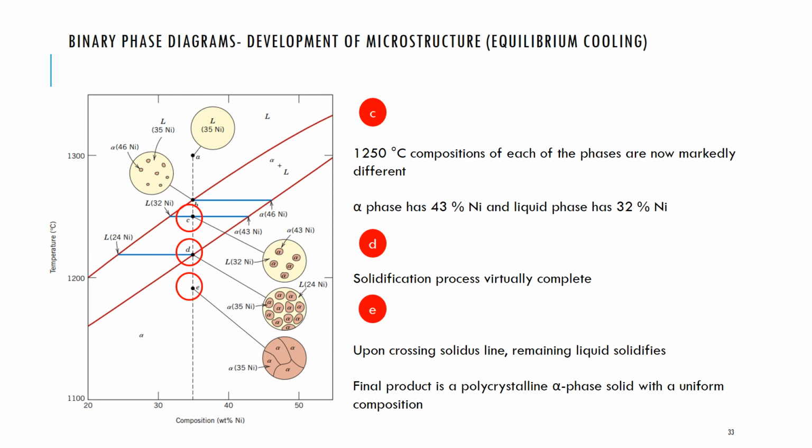As I move down to, let's say, 1250 degrees Celsius, or point C here, I've still got two phases present. But the composition of those phases looks different. There might be more copper now in the solid phase, for example, and the amount of nickel will change in the liquid phase. And that's because the system is responding here and readdressing that equilibrium.